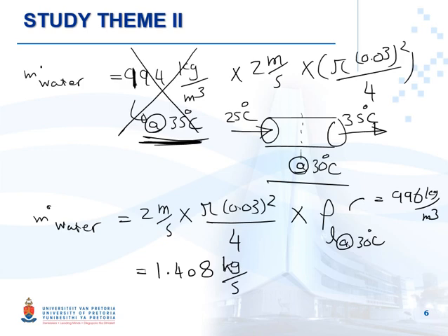The same when we want to calculate the Q dot. We said that is m dot Cp (T out minus T in). We are just calculating for the cooling water. So again, the Cp should be read at 30 degrees.